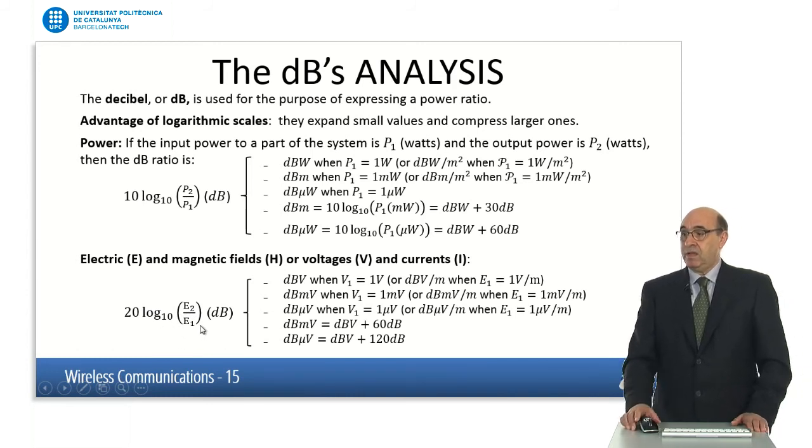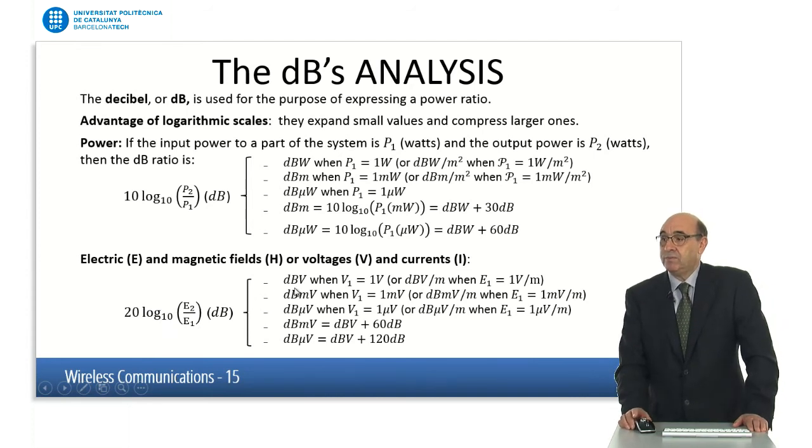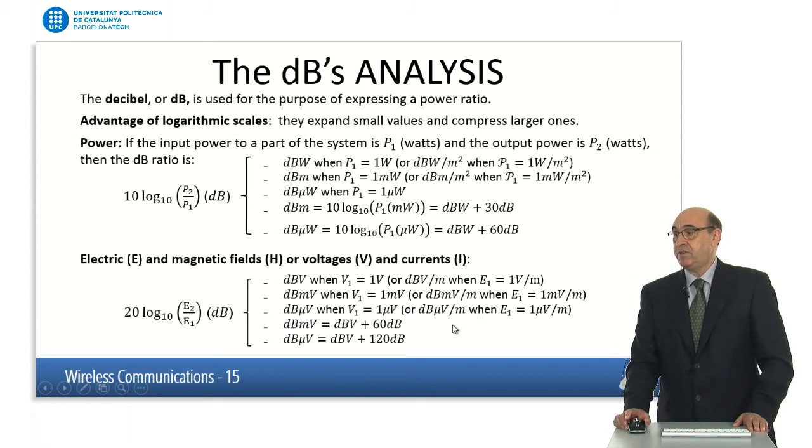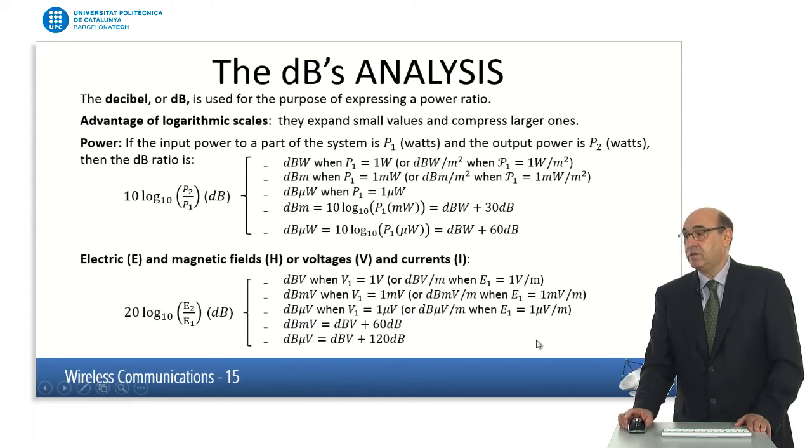And here we have new units to talk about. We talk about dB volts when the reference is 1 volt, or this is a very frequently used one in broadcasting, dB microvolts, or if you are talking about fields, dB microvolts per meter. And this is the reference. In one case it is 1 microvolt or 1 microvolt per meter. And once again, you can